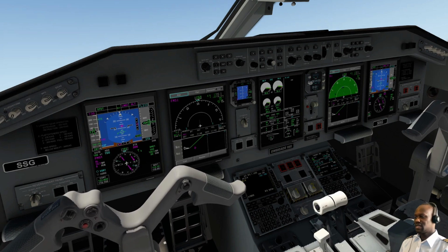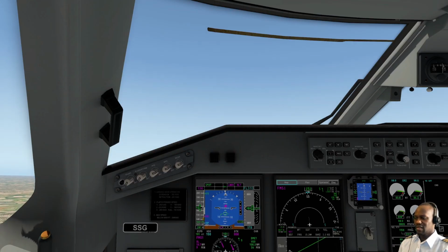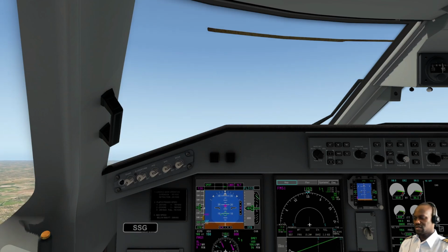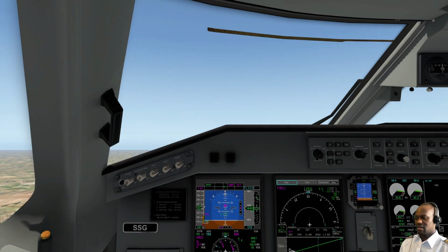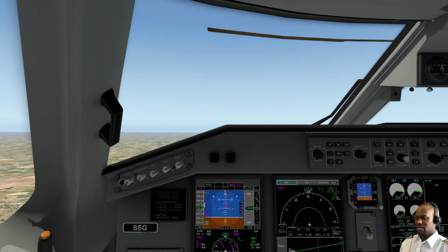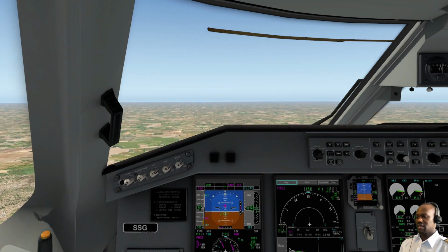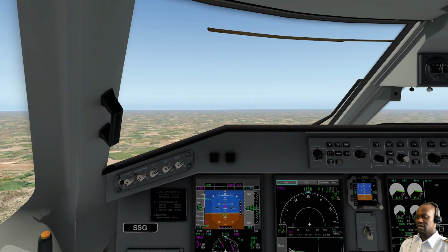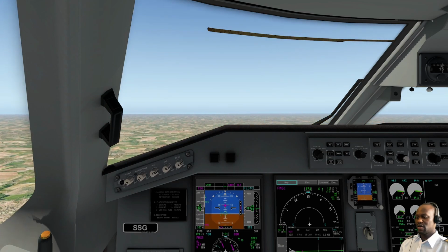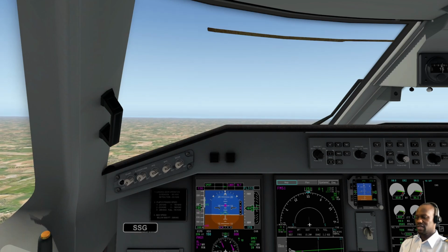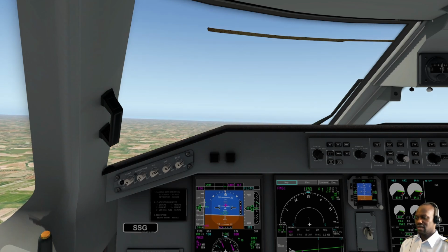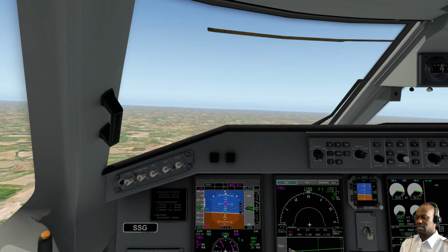Right, so these messages have woken up the pilots. Pilots can now recover and figure out what was going on. But once we are above MSA, I can level it off at 7,000 feet and let the speed accelerate to about 210 knots, maintain 7,000 feet, and figure out the situation.